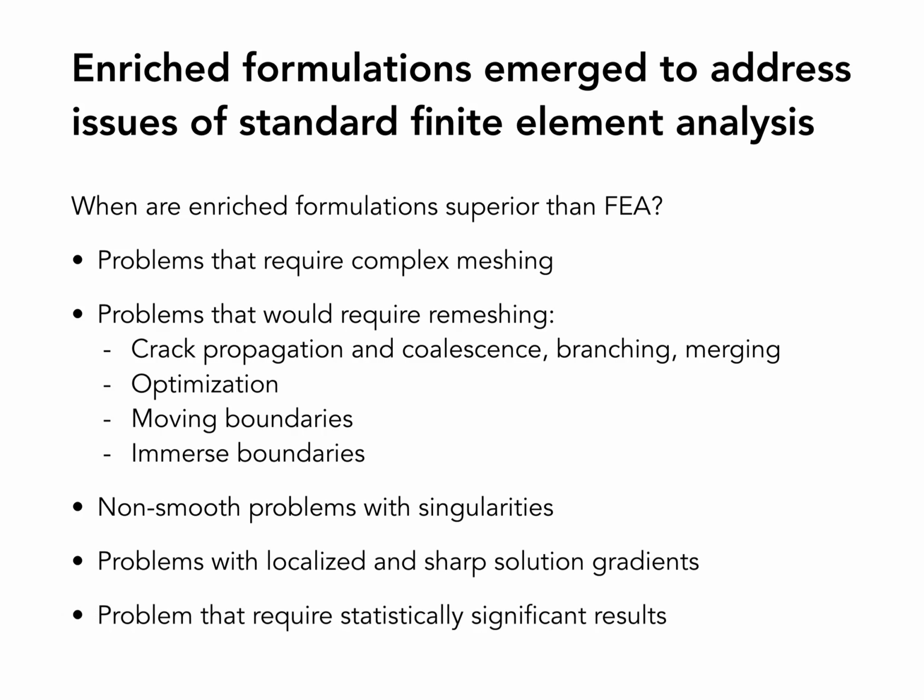Another thing you can do, since we're not dealing with the mesh, is use always the same simple, structured finite element mesh. Then these methods are very powerful to come up with statistically significant results. Let's say you are analyzing the microstructure of a material that is composed of randomly placed spheres.